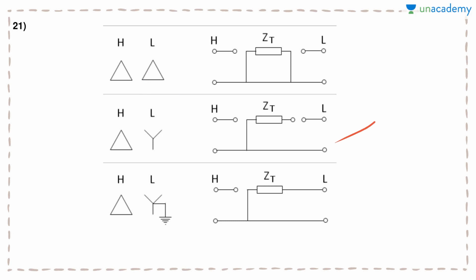And another example is we have the primary over here as shunt connected, the shunt switch is closed, that means the primary is delta, and in the secondary connection the series switch is not closed but open, and there is no shunt switch closed. The shunt switch is also open, that means delta is not present, and star with grounded neutral is also not present. That means only star is present and the neutral is not grounded. So the series switch is open in the sense star connection is present but the neutral is not grounded. If the shunt switch is opened, the delta is not present in the secondary.